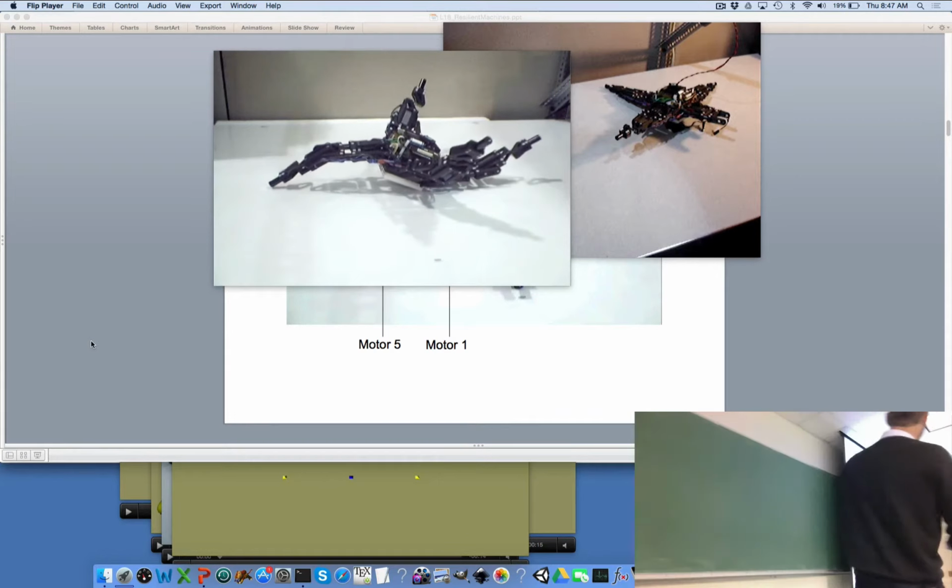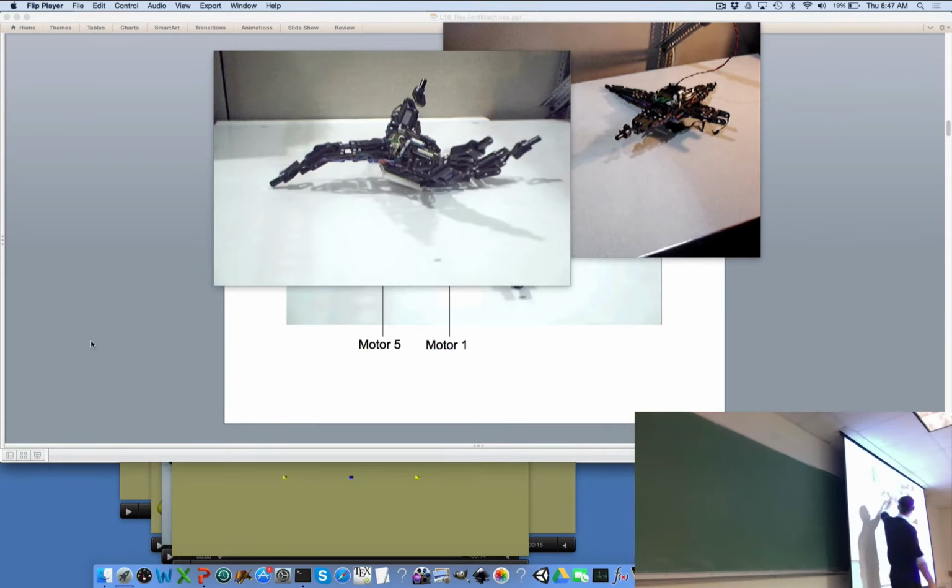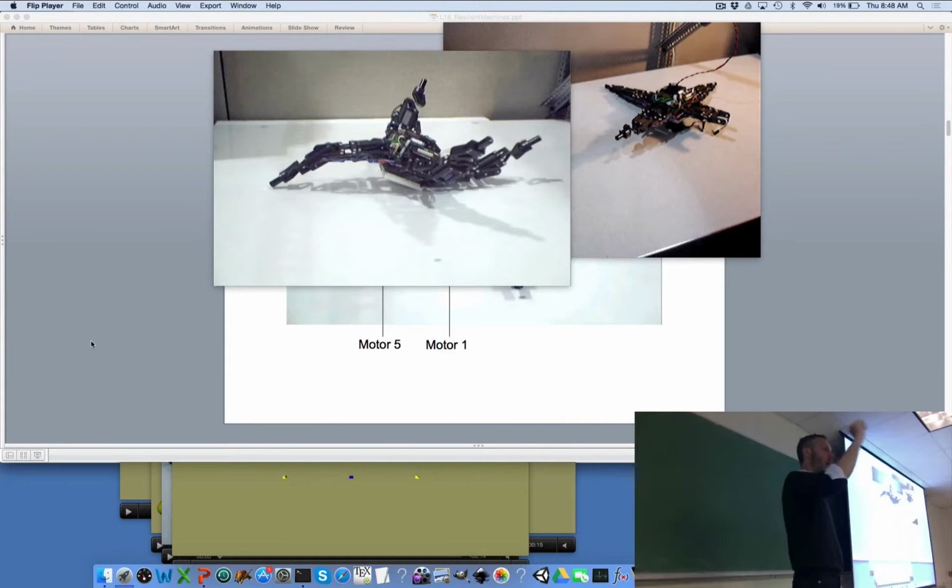Okay. So the robot rotates motors 1 and 5 down and the other motors up, and it records at the end of this motion 2 numbers: how much it's tilted forward and back, how much it's tilted left and right. So the physical robot now has 1 data point. When I rotate my 8 motors in this way, I get this sensory repercussion, right?